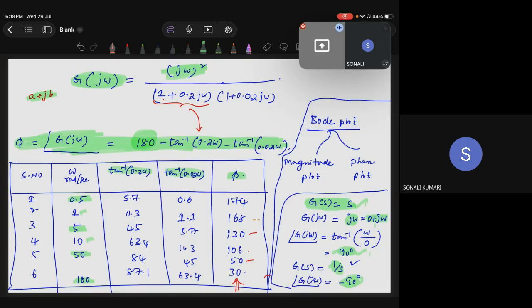Okay. So how many poles we have? So the poles are two. Okay, but they are not j omega plus j 0. They are something like this is a. This whole thing is jb. Am I correct? Yes, sir. So the angle will be tan inverse 0.2 omega by 1. That is this term. Similarly, the other term also this one.